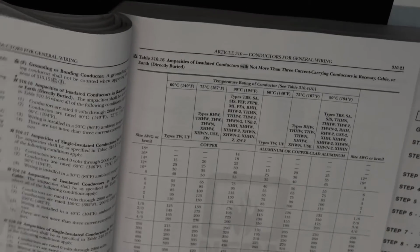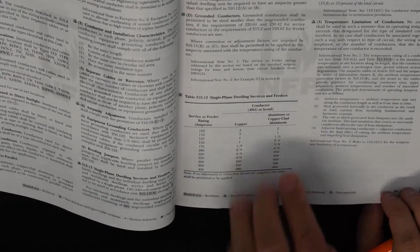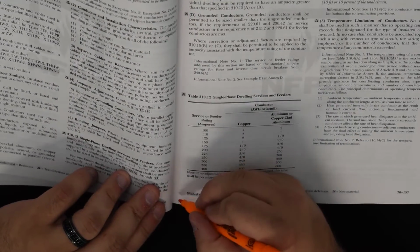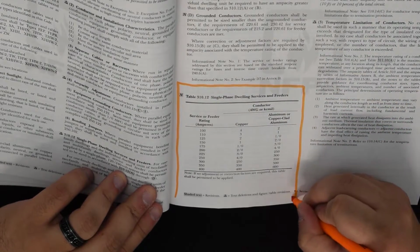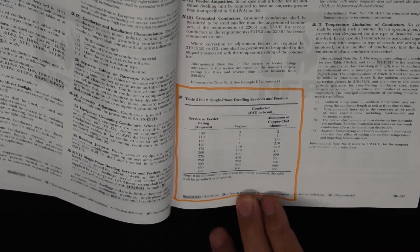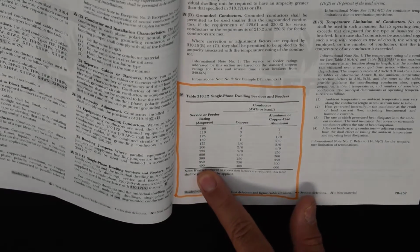Now we're going to go to a different section. We're going to go to Article 310.12 table. This table says single phase dwelling services and feeders. We're going to take our dark color highlighter and box this table in, just make it pop off the page. And this table is going to be referenced at the end. If we've got a service or feeder rating in amps, it's going to have a list from 100 all the way to 400. It's going to tell us what size wire, whether it's copper or aluminum. It's a simple reference table.